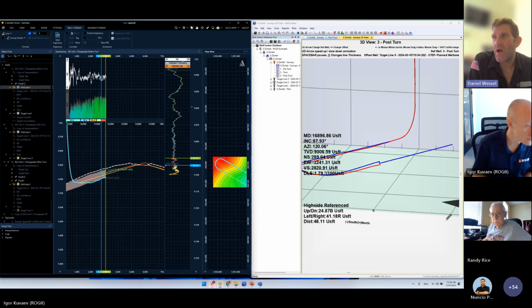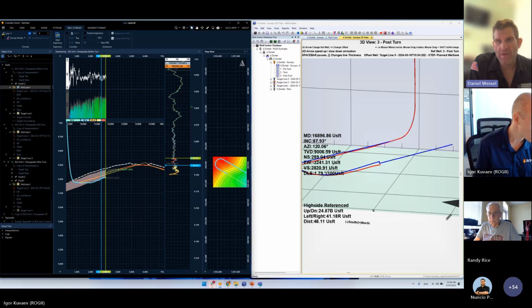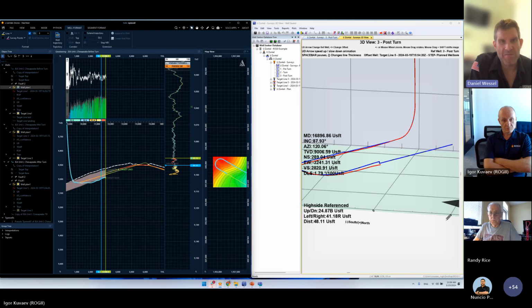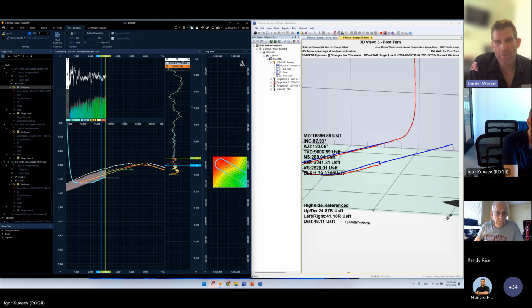We're taking the offset based off the well plan rather than the bit projection, because the well plan is the line that the directional driller is trying to follow. The actual new well plan that is being created has that stepped profile up to the TVD specified by the target line. So really where that plan ties onto almost doesn't matter. We tie onto the current well plan so that we have that traceability, that audit of what the well plan changes were.